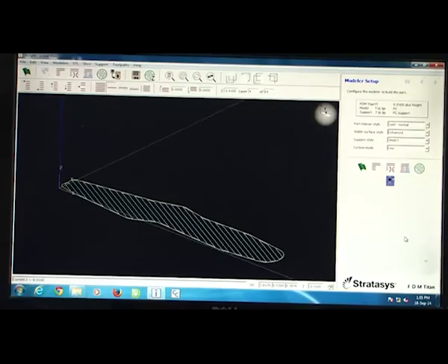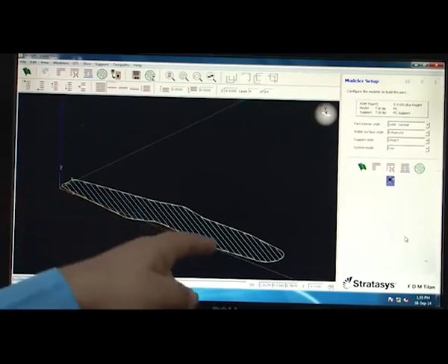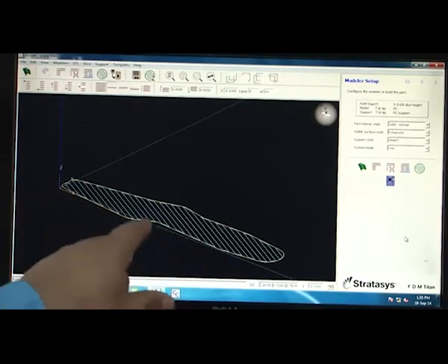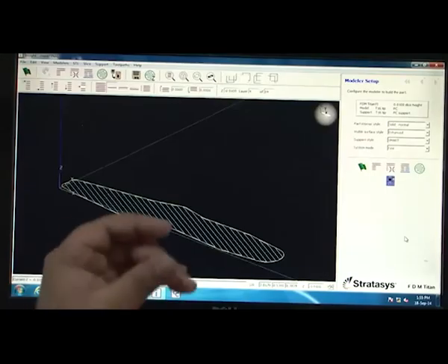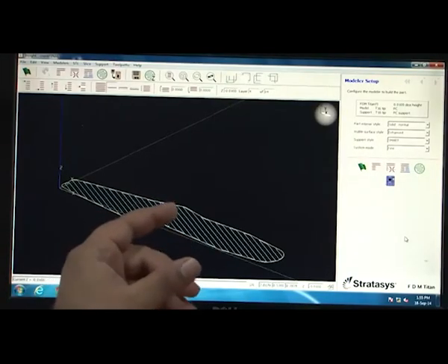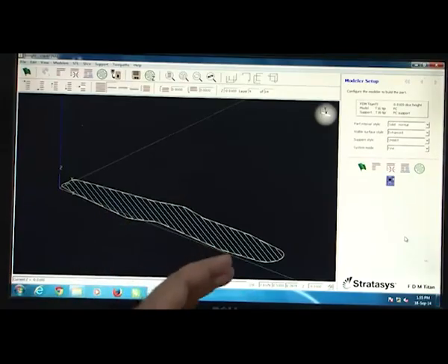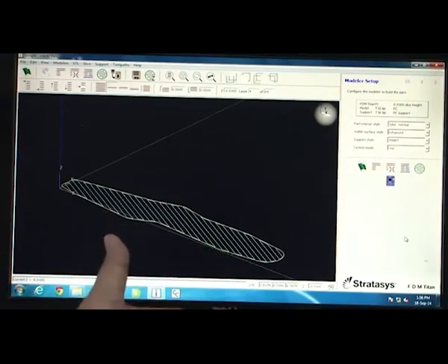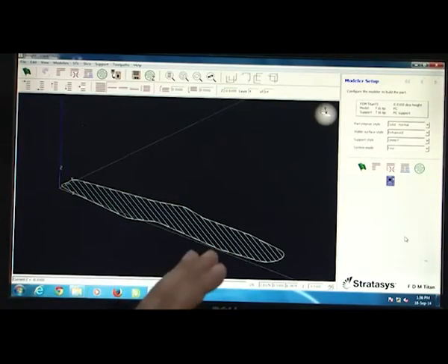As you can see, it is much lesser in terms of the density of the material, because it will be like a honeycomb kind of a structure. The distance between the two dispensing points would be much more, because this is something which is in any event going to be sacrificially removed, and the material has to be as low dense as possible, so that we can make lesser losses than is possible. So therefore, this is how actually the whole system is